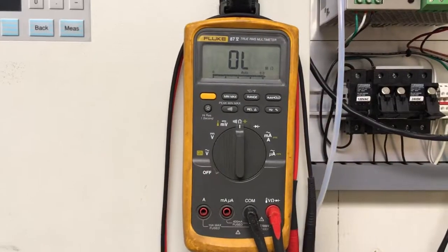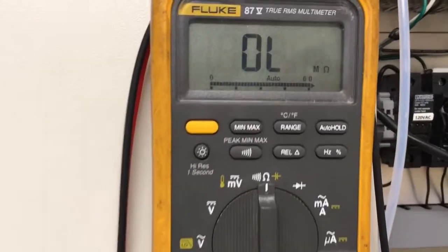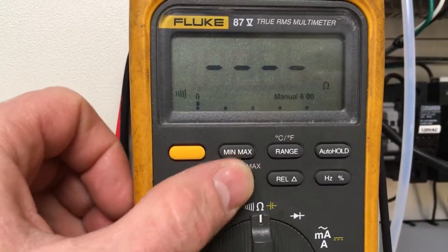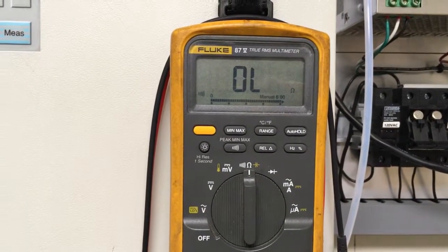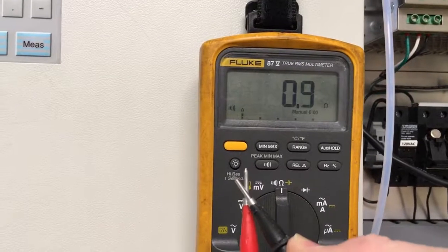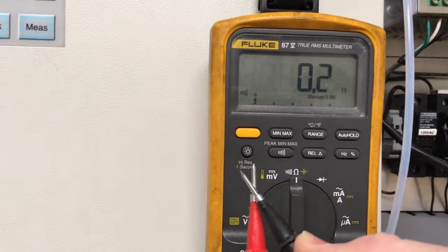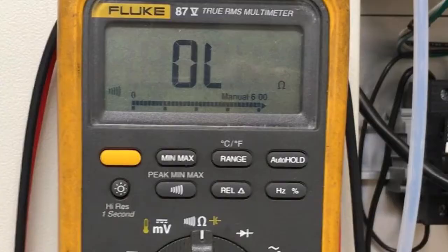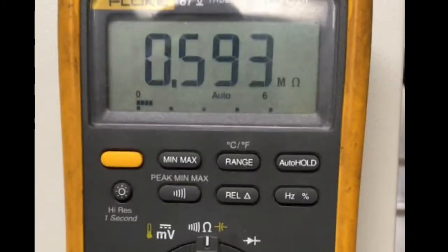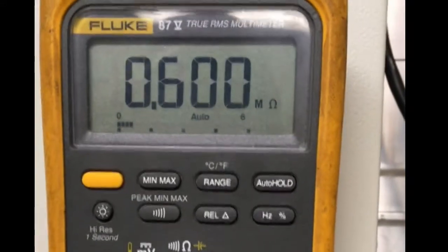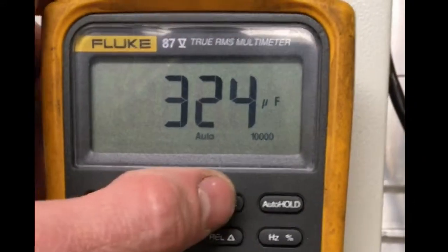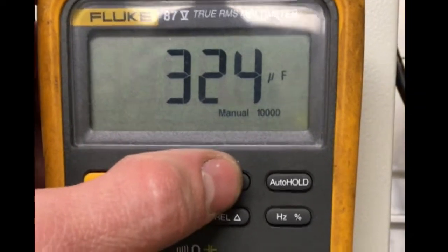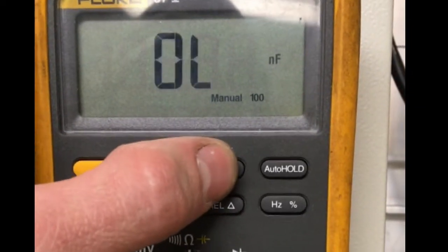While in this mode, a continuity check can be performed. To activate this function, press the button indicated by the tone symbol. While in this mode, measurement with low resistance will produce an audible tone. The measurement range for this mode will be the lowest resistance scale. Pressing the secondary function button at this dial selection will switch the meter to capacitance mode. In this mode, the meter will provide an auto range capacitance measurement with the option for manual range setting.